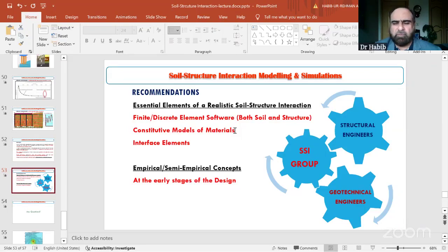It depends on so many factors. It's a big process, and we move from, for example, shallow foundations, then to the feasibility of raft foundation, then to ground improvement, and then among ground improvement we can have different cases. So there are many steps before we reach a conclusion that ground improvement is required, and then what type of ground improvement techniques are possible for a specific site.